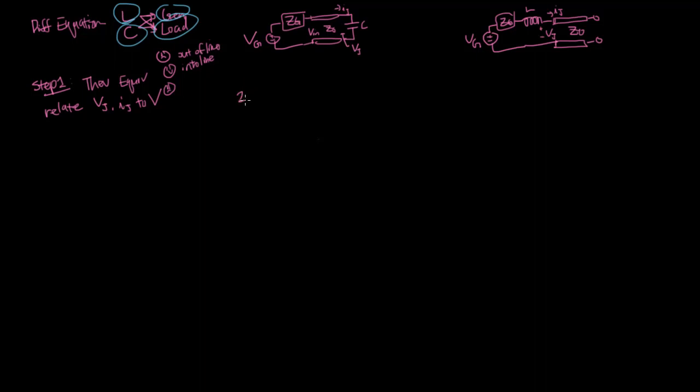We have a 2V plus source, with an impedance that's the characteristic impedance of the transmission line. And then this is our voltage at the junction. This is our capacitor, and our current in the junction is defined in this direction. Let's do that for the inductor case.